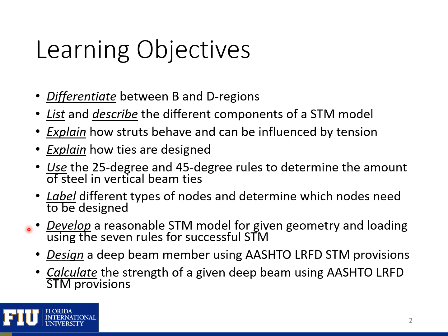Develop a reasonable Strut-and-Tie model for a given geometry and loading using 7 rules for successful Strut-and-Tie modeling. Design a deep beam member using the AASHTO LRFD Strut-and-Tie method provisions, and then calculate the strength of a given deep beam using AASHTO LRFD.